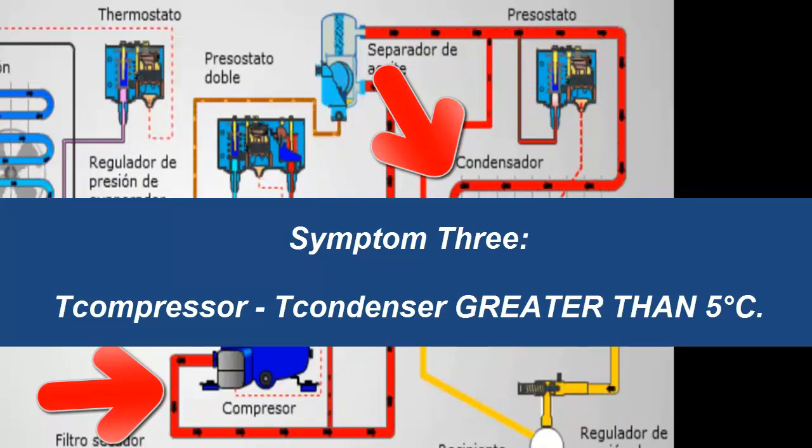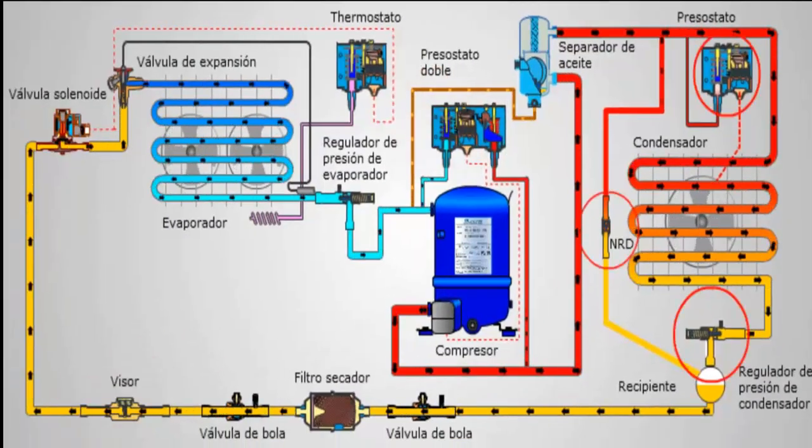Well, with these three symptoms we can focus the failure of the equipment on lack of refrigerant.